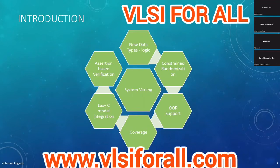Then there's coverage. Coverage is a metric used everywhere, and every verification engineer uses it to say that their design is completely verified. Though for a complex design, it's never 100% verified, by using coverage we say it's 100% verified. Coverage is basically a mutual agreement between a verification engineer, a design engineer, and maybe architects. They sit together and agree on which scenarios to cover out of millions of scenarios. By scenarios, I mean the combinations of the inputs, including the FSM states.